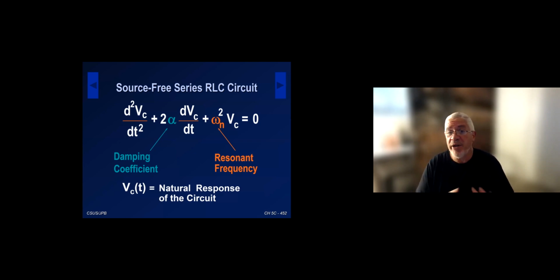So when you get a differential equation here, I'm going to ask you to identify the damping coefficient, which is that constant alpha. It's essentially the coefficient associated with this first order derivative divided by 2. Okay, so this assumes, again, we agree to normalize our differential equation so that the highest order derivative has 1 coefficient.